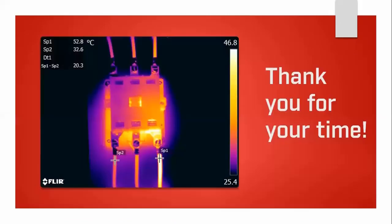Now, going back to this image, we looked at this just now, and you might have an idea as to what the problem is. The actual problem with this contactor was that the internal components were pitted and had gone high resistance. So on the right-hand phase, we've got an elevated temperature on the bottom cable, and the heat from the contactor was conducting out through that cable.